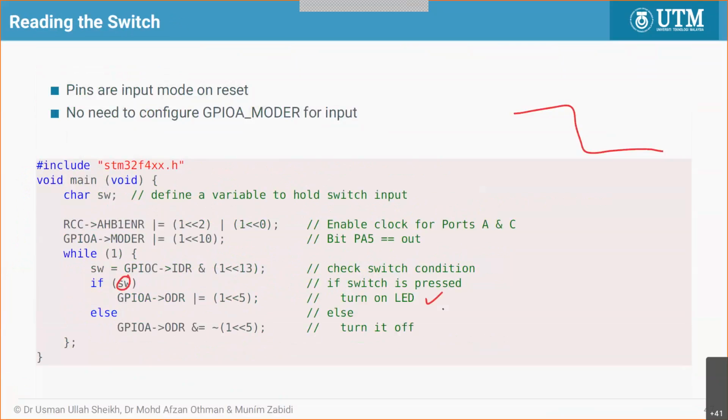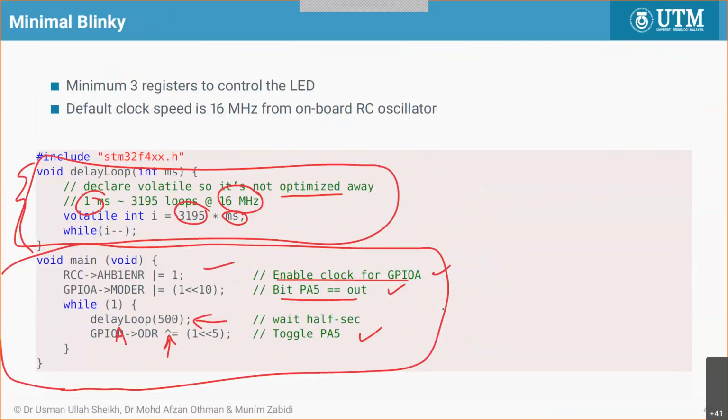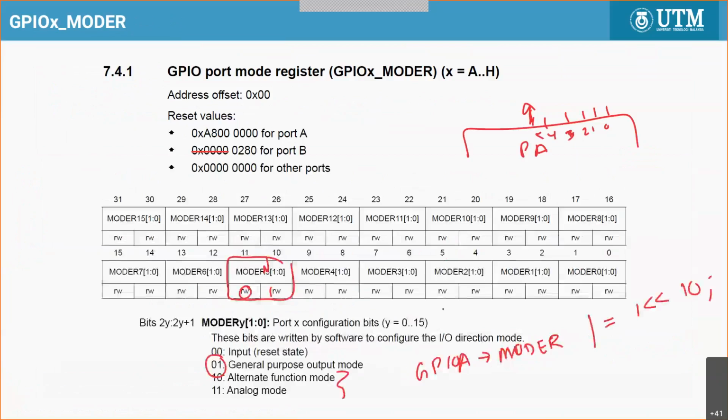Hi, Doctor. Yeah. Just now the page 45, we're going to set the GPIO pin, right? So why do you shift then? Oh, it's because you're not sending data out yet. You are just changing the mode of the pin. And by default, the pins, they are all input mode. But you want this LED, which is connected here, so you have to change at least this one to become output. So to change pin 5 to output, you have to go to the bit that controls pin 5.